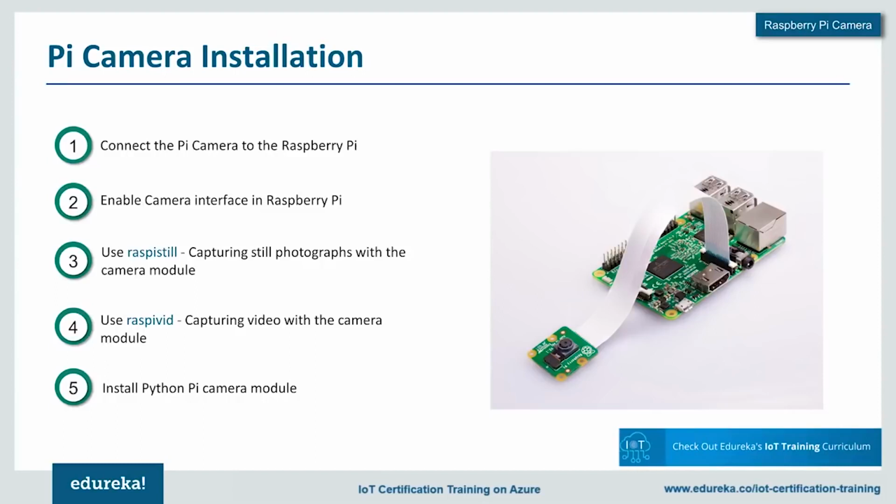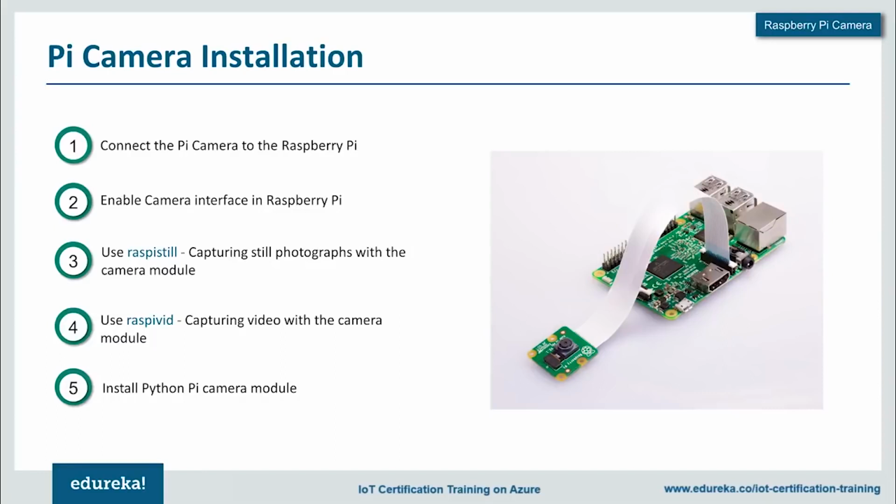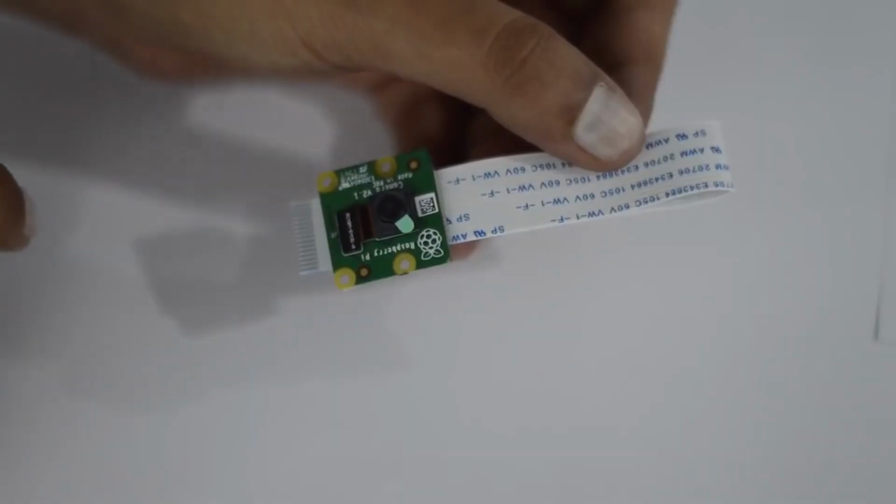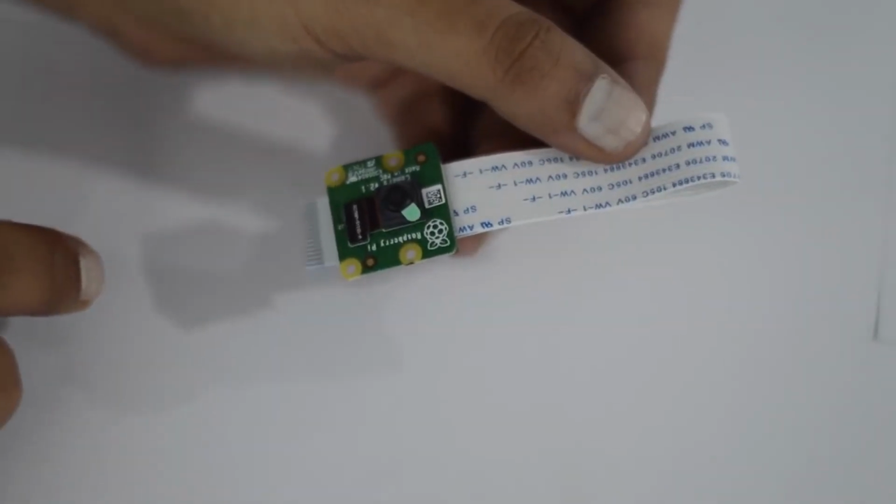This is very important because we've used 3 camera modules and we've managed to burn out 2 of them. So please be careful, because this is a very delicate ribbon and also a very delicate module. Let me help you understand how you can attach the CSI cable to the Raspberry Pi, and then once you've done this, how to enable the camera as part of your Raspberry Pi as well. So this is my Raspberry Pi camera, and this is version 2 of the camera.